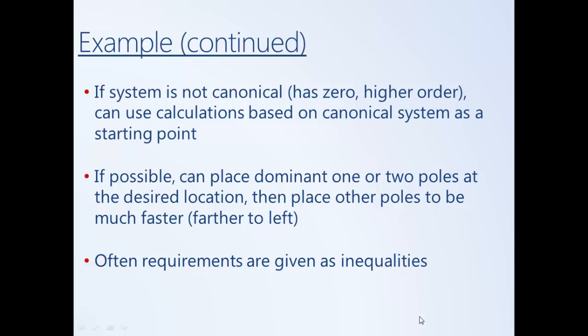In that previous example, we were shooting for a settling time of exactly 2 seconds and a peak time of exactly 1 second, but in general, requirements are often given as inequalities. It's generally not required that the settling time be exactly 2 seconds. It's generally the case that the settling time be less than 2 seconds.